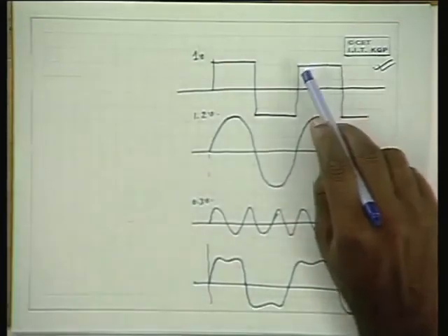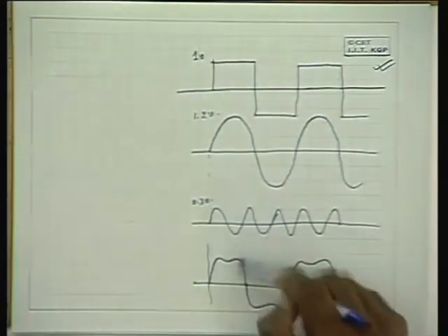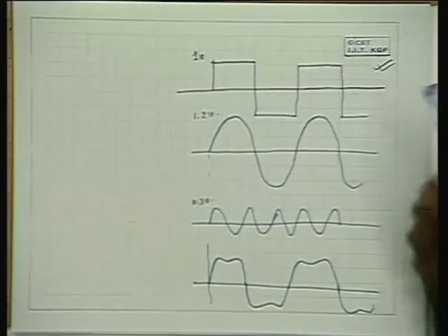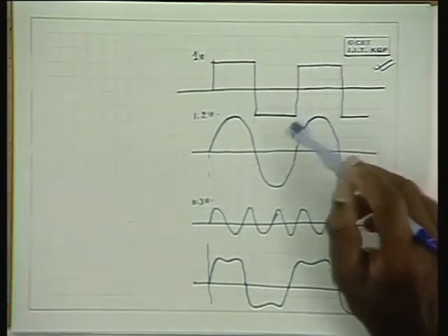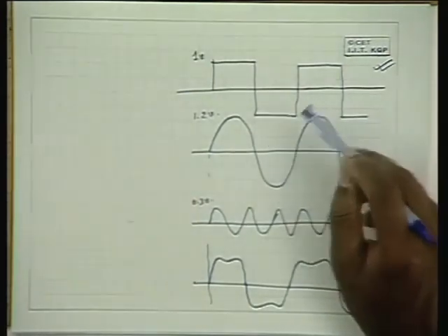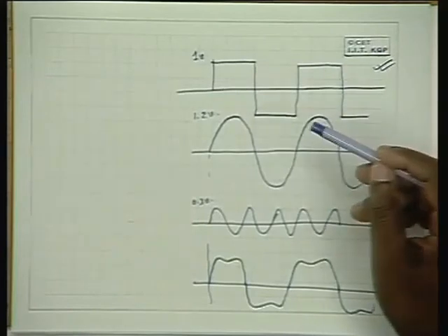Asymptotically, when you consider an infinite number of components, the error almost tends to 0 in this particular case. Yeah, there is a doubt somewhere. So, why are you always taking the odd harmonics? In this particular case, depending on the shape of this signal, the symmetry of the signal is such that when you add the odd harmonics, it makes up. If you try to add the even harmonics and find a solution, you will find that the even harmonic amplitude is 0.